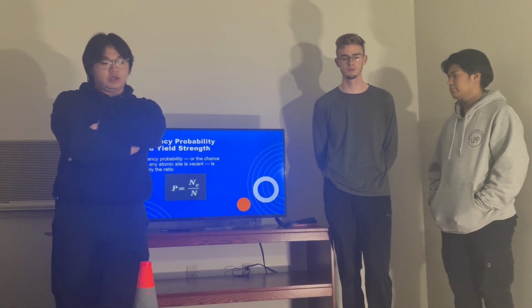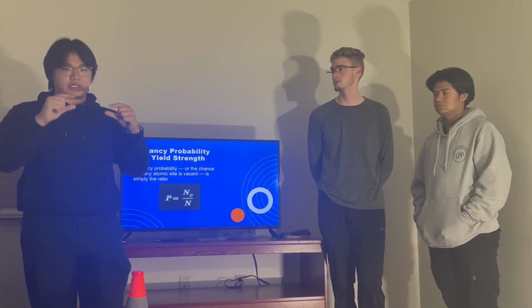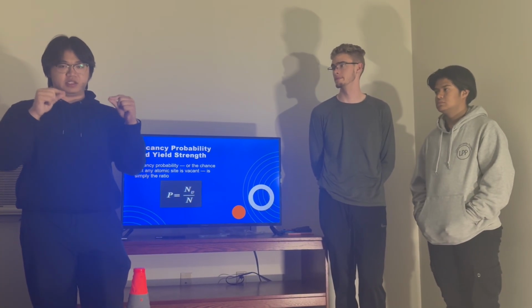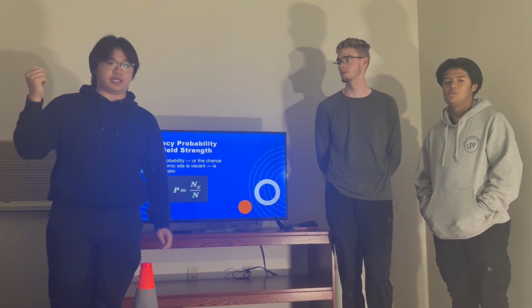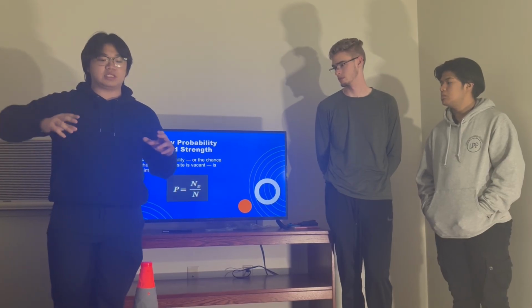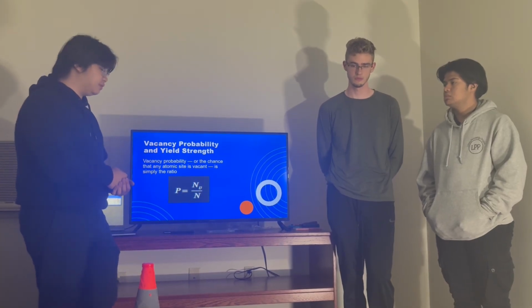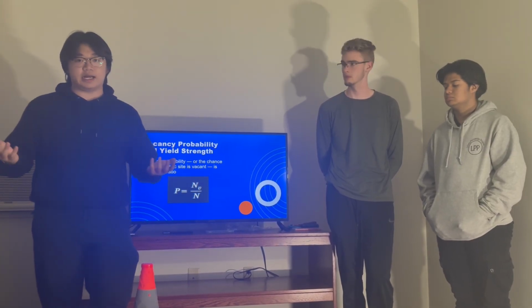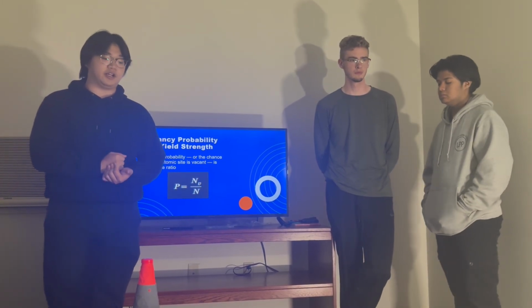And so for aluminum, if you've ever played around with aluminum foil, you'll realize that with a thin sheet of aluminum foil you can bend it back and forth all day and it won't break. But if you try to do that with a sheet of iron, with a sheet of titanium, with anything like that, a very brittle metal, it would just fracture immediately. So that's one of the reasons why aluminum, although light and ductile, is relatively soft compared to iron.